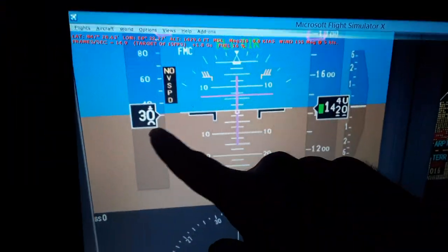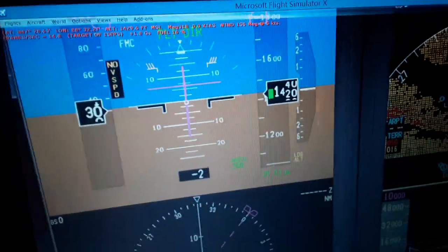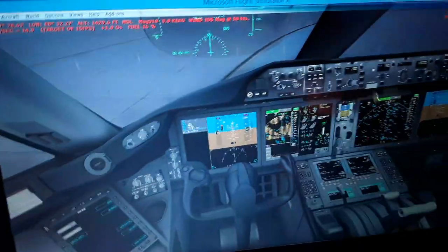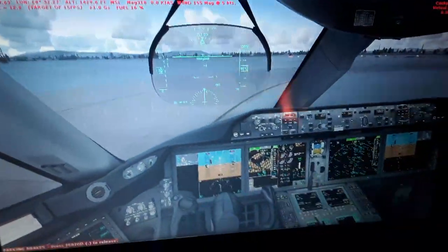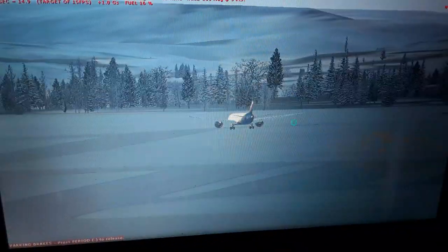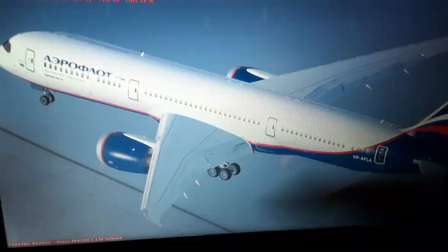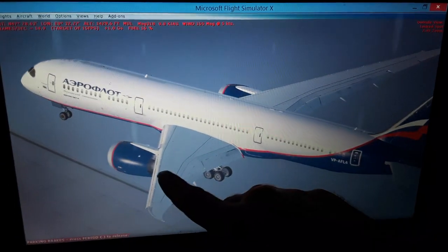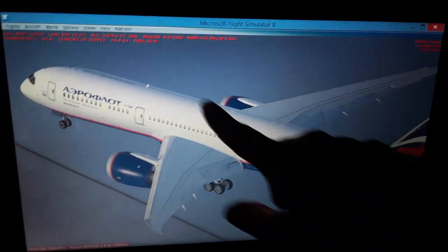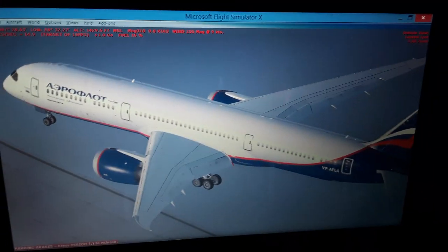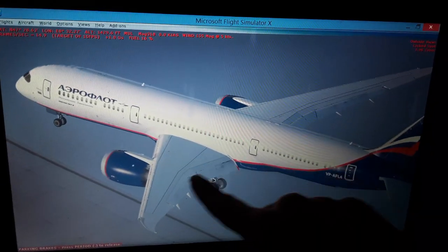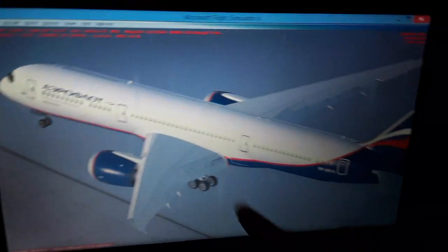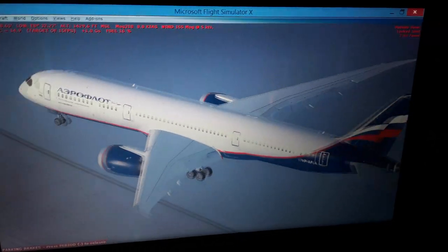You have to keep your airspeed and your angle of attack below the stall speed as you fly, so you won't make the aircraft stall. As I told you, here we have the aerodynamic position and the center of gravity, pretty much here. The load from the wings, we have the fuel tanks here and here in the center tank.